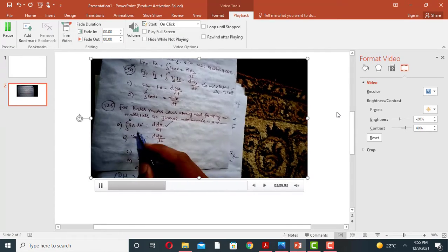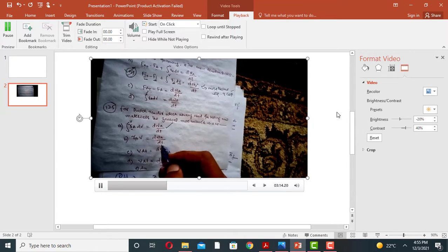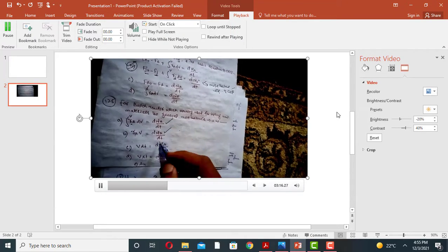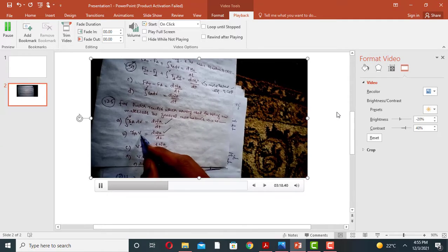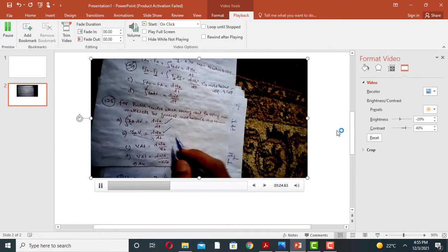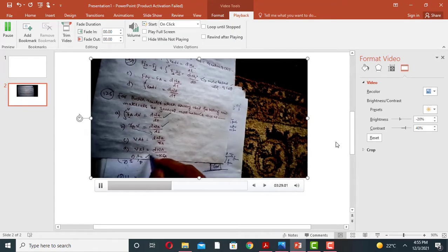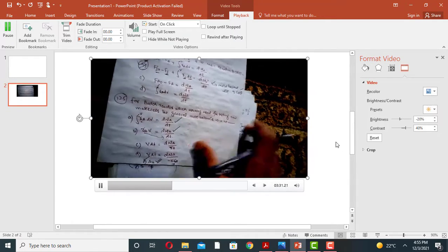If the rate is constant, then rA times V equals dNA divided by dt. Rearranging this, rA comes to the denominator, so dNA by rA, and we know that minus rA is equal to kCA. So all of them are correct.